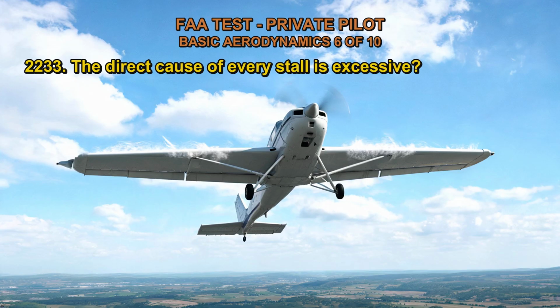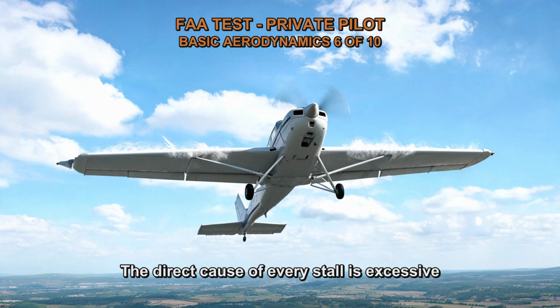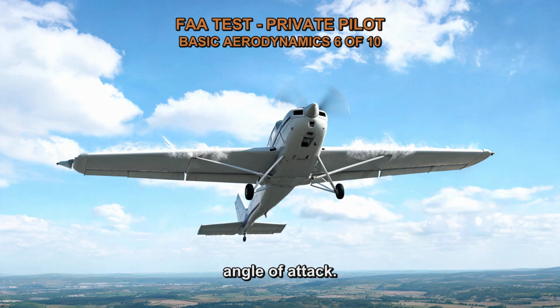2233. The direct cause of every stall is excessive: A. Angle of attack. B. Density altitude. C. Upward vertical velocity. The correct answer is A. The direct cause of every stall is excessive angle of attack.